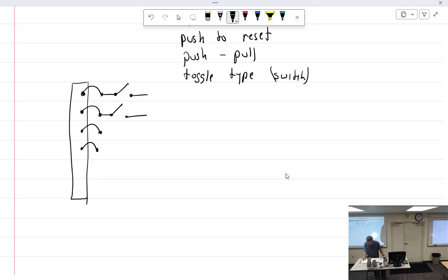So when it becomes overheated from excessive current, it bends away from a catch on the switch lever and permits the switch to trip. Then there's the trip-free circuit breaker, which will allow the circuit to be broken even if the pilot holds the button in, which pilots have been known to do. So in other words, the circuit breaker keeps tripping.